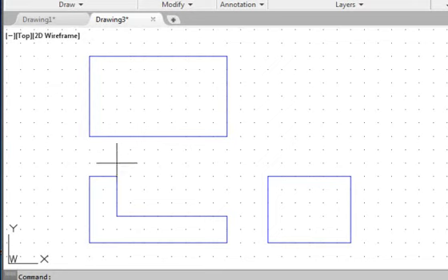Move the cursor to the corresponding corner in the front view and notice AutoCAD shows us the alignment to that corner. With the Running Object Snap mode switched on, we can go to the intersection that is lined up to the corner in the front view. Move the cursor on top of the same corner and we can create the line we need very quickly.